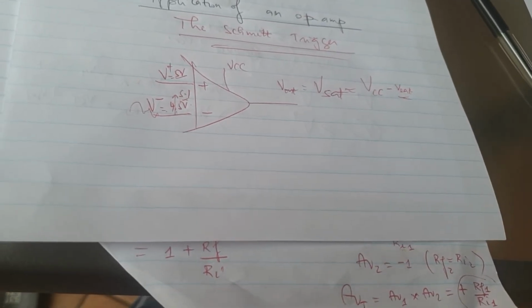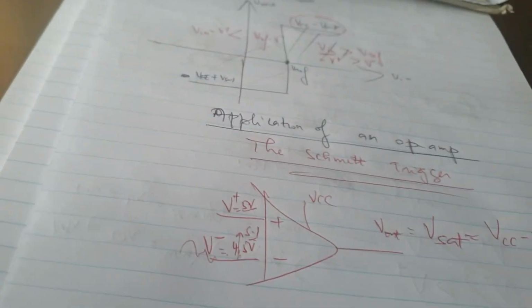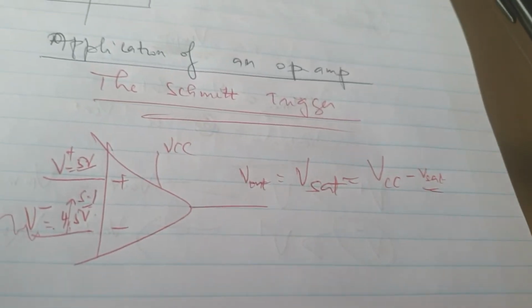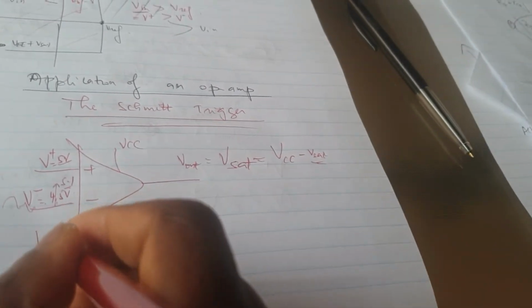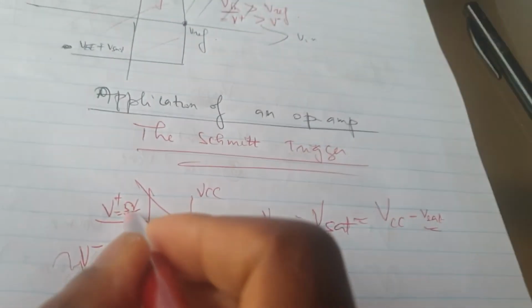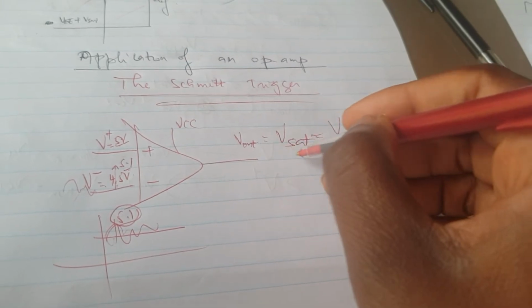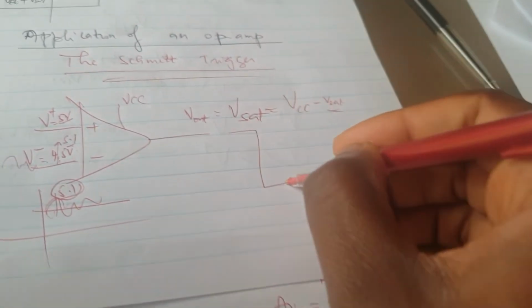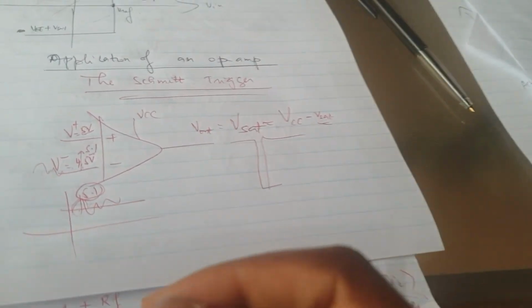The sensitivity comes in the fact that the reference could vary. Maybe resistances, remember they've got tolerances, or due to temperature change or any form of noise around the signal, could move the 4.5 DC, which could be superimposed by some noise signal that could push it maybe to 5.1. Automatically when it just reaches 5.1, meaning slightly higher than 5, the output will swing from that much to lower quickly. So you get that effect, and that's where the Schmitt trigger comes in.